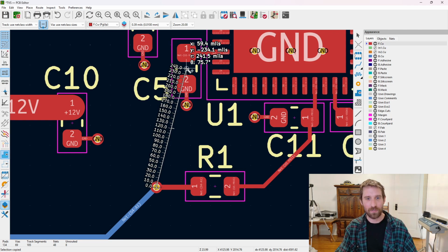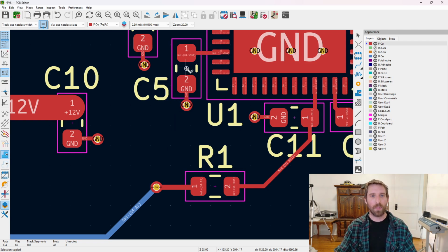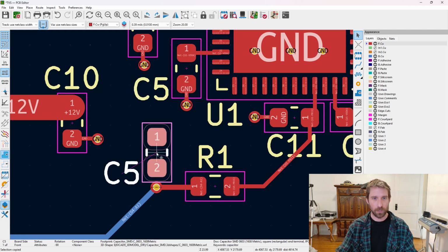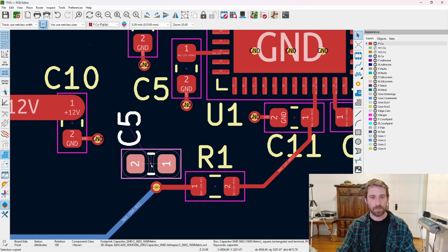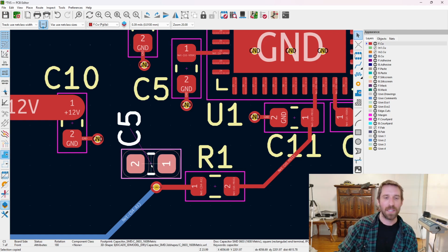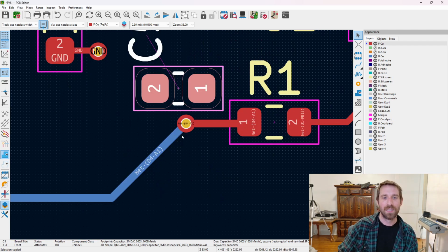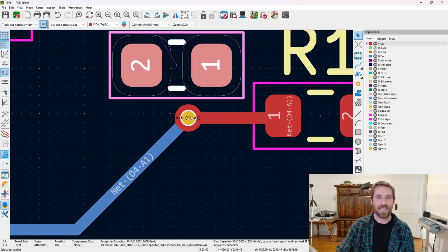And as we saw from our Saturn PCB, that's a lot of inductance right there. So the way to solve that would be to do this. Add a decoupling cap in your schematic, put it right next to this via.